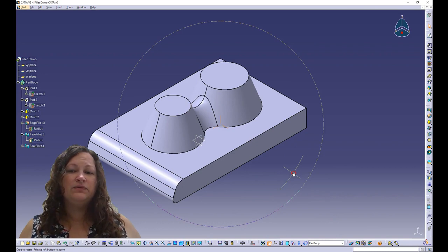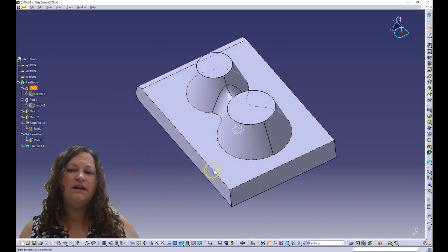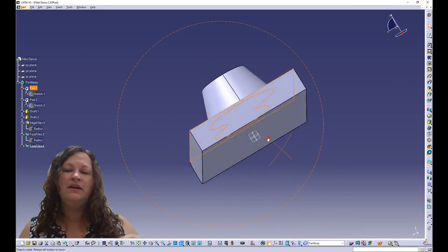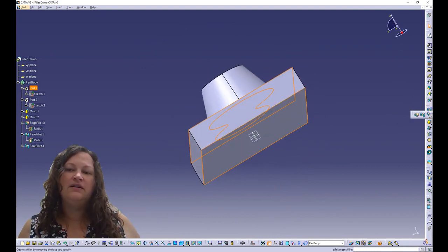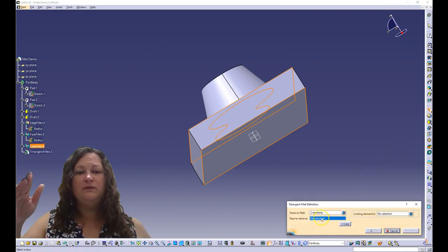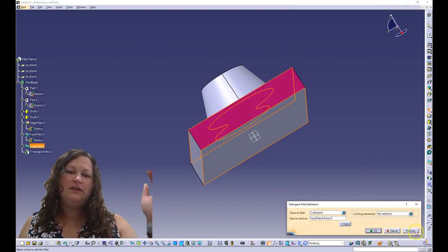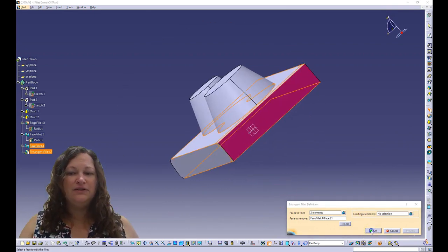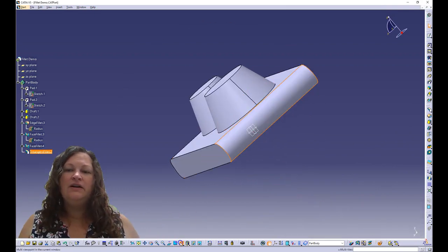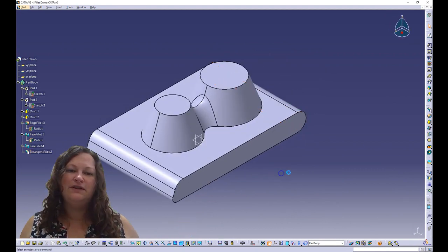Next, let's do a tri-tangent fillet, which will allow you to take two parallel sides. They don't have to be parallel, they just have to not touch. And what we'll do there is then remove the whole face between them and make a smooth arc all the way around. So essentially making a tangent end arc between those faces, but using the fillet tool.